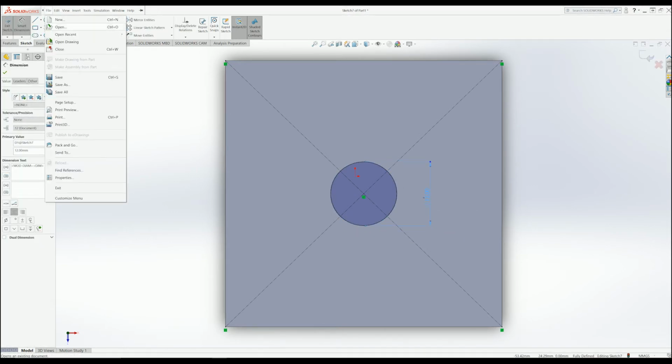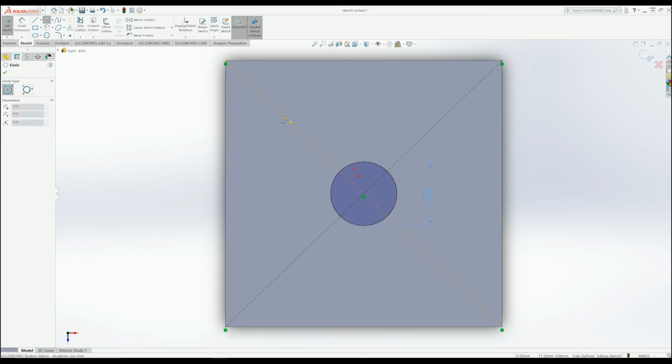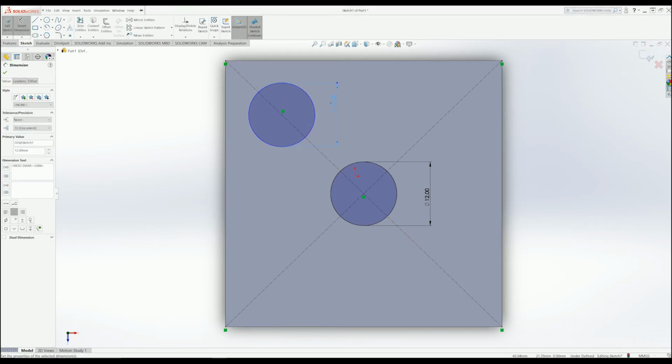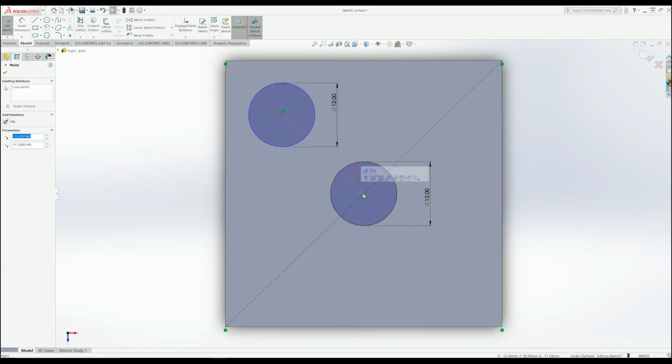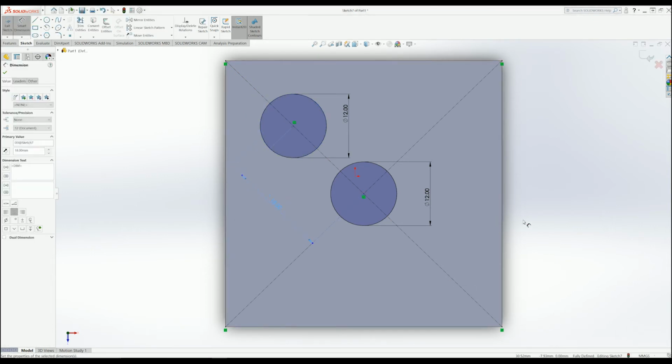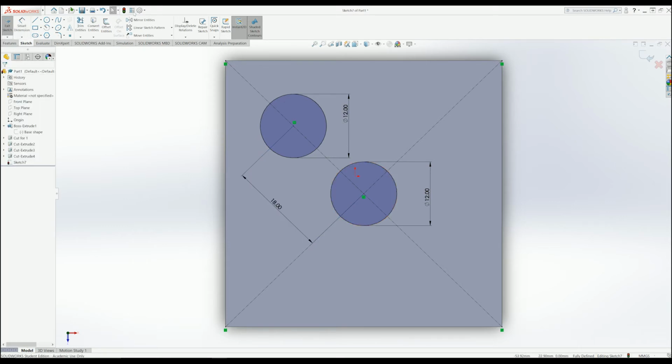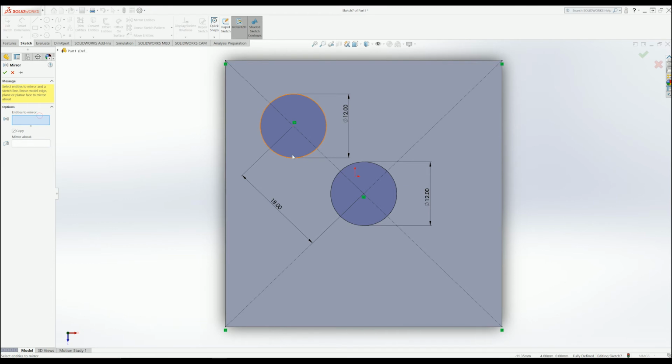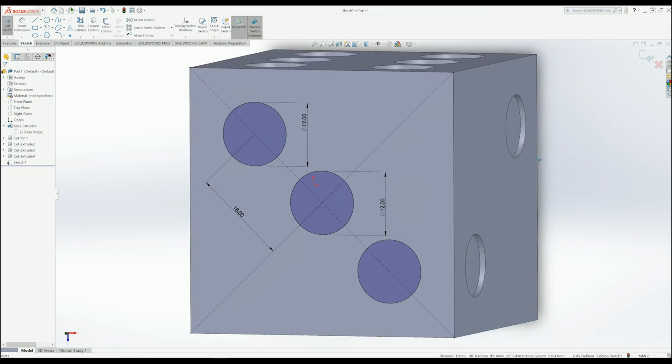Okay, so lovely, 12. Let's do a circle on this line. Smart dimension, 12. Let's make this one a certain distance from this point here. So let's do smart dimension, distance. Okay. So let's do this as 18, see how that looks. Okay, so we've got 18. And then, as we've done before, we're going to cheat a little bit, do a quick mirror about this line, and then we've got our next shape.